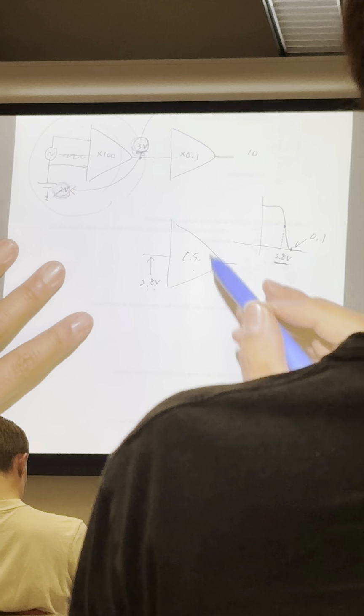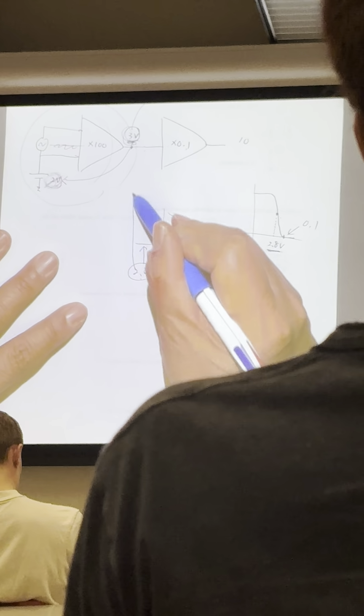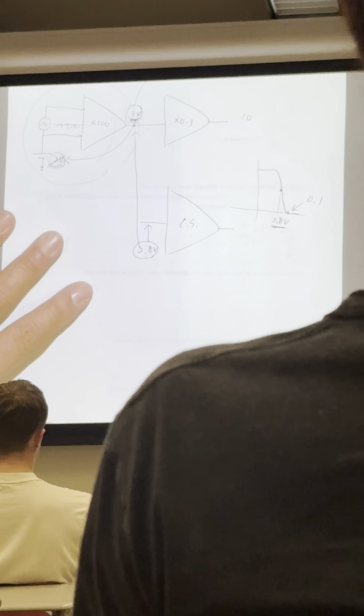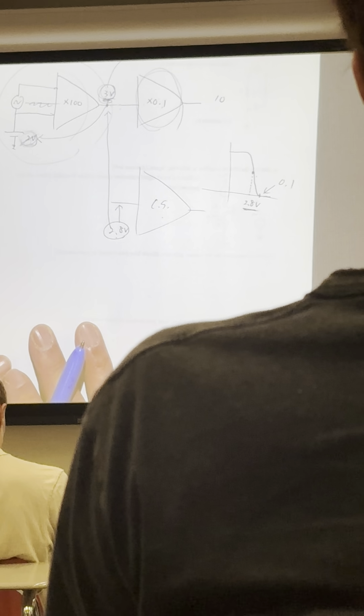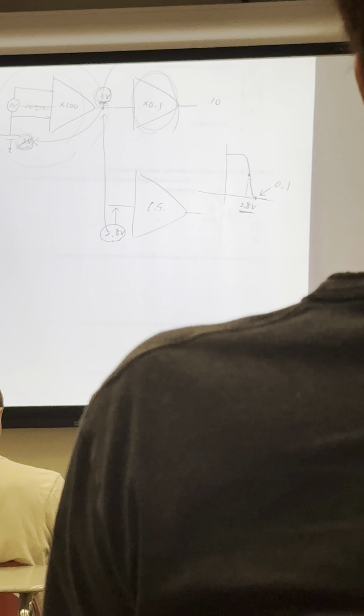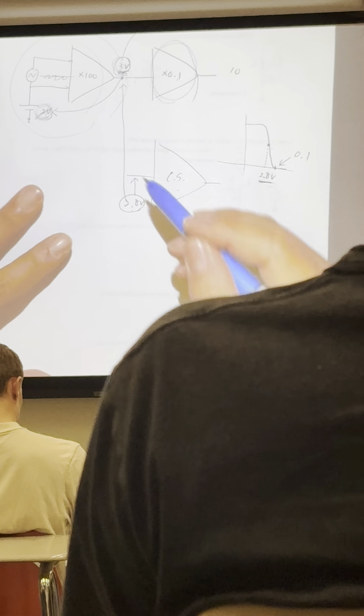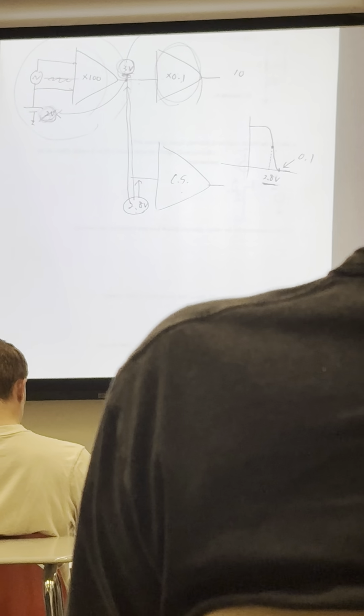Okay, that's fine. Then you need to change this one to 3 volts, right? So what you need to do now is change the size of this transistor or the biasing current of the second stage. But whichever direction you use doesn't matter. What you need to do is make these two numbers the same. That's the most difficult part of this simulation.